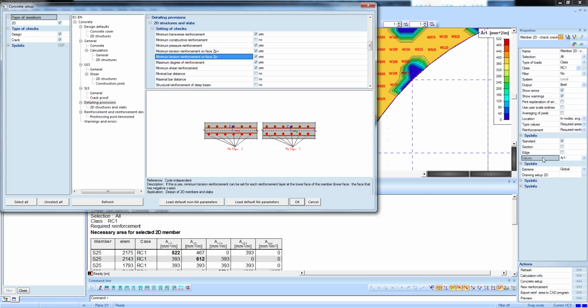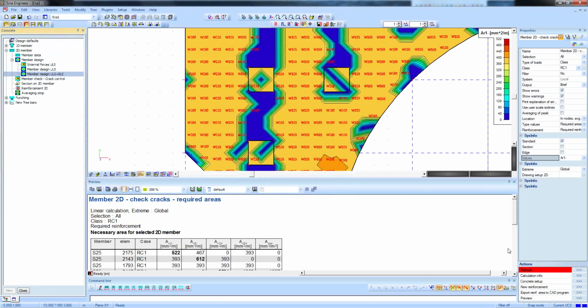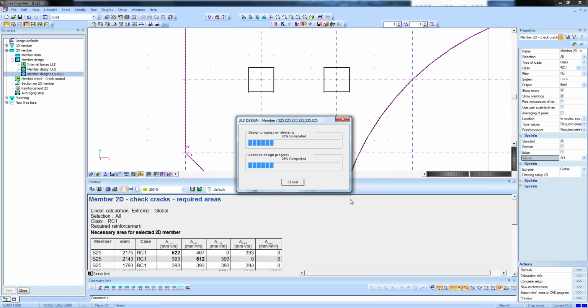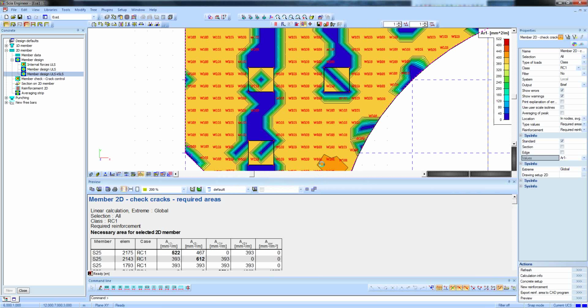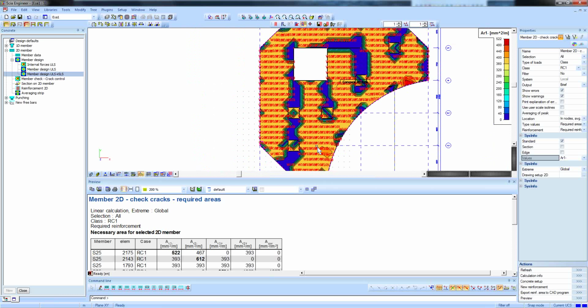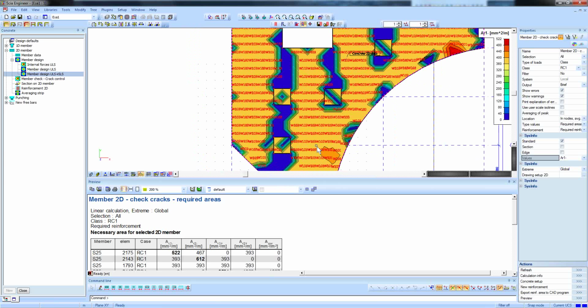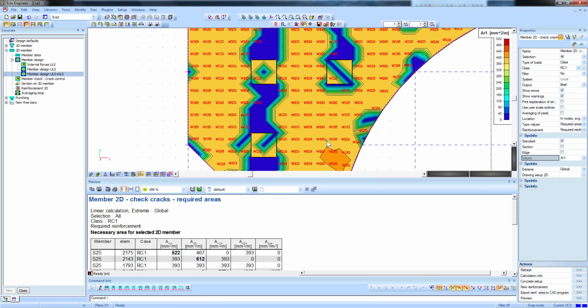We are using AR -1, -1. So the minus means that we are on the bottom side. So if I would tick this off, for example, and choose OK again, then I would have to recalculate my reinforcement. The end result which I get then has not changed a lot, so there is also a different option, minimal reinforcement, which has importance. It has changed maybe a little bit, I'm not sure, but the warning is related to one of those options which I have just shown.